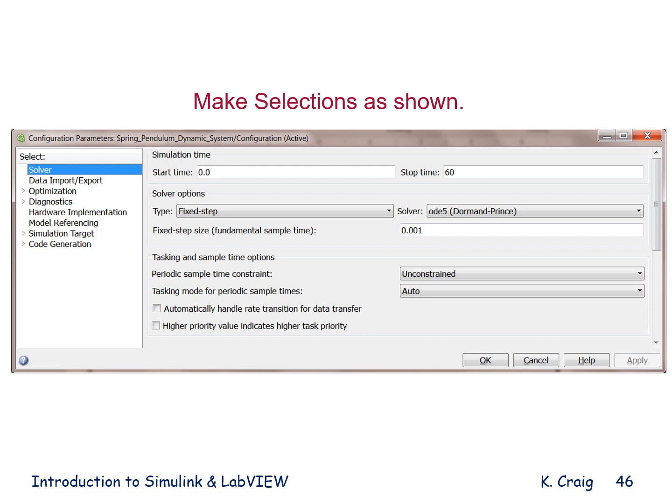The integration algorithm I use is, in this case, ODE5. Well, you have a choice of many different algorithms to use. MATLAB in its documentation will give you guidelines as to which algorithms are preferred for certain situations, such as systems or models that have many nonlinearities, or models that have a combination of very slow and very fast dynamics.